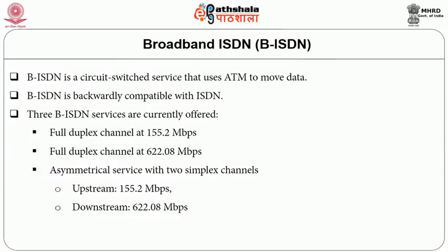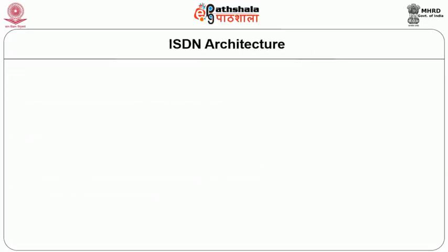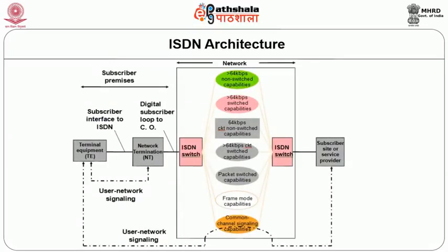Many times, if you look at the services, people provide this kind of ratio in the bandwidth, because everybody will be interested in downloading rather than uploading something. So download will be at least 4 times bigger than upload. We will see a 1:4 connection, 1 for upstream and 4 times for the download stream. Here it gives a little more detailed view with other terminals used. Between the terminal and the digital exchange, you have a network termination, NT, or the equipment is called NTE, network termination equipment.